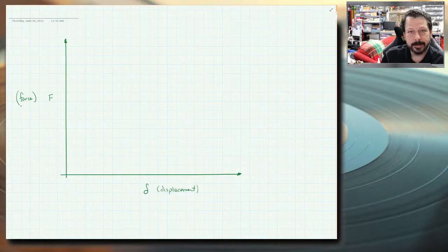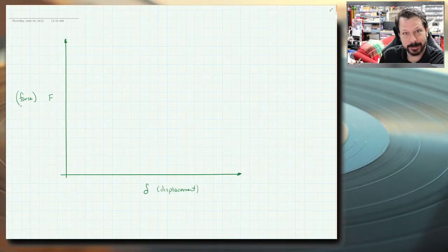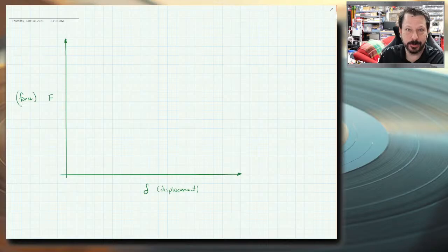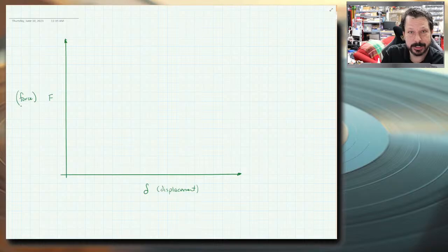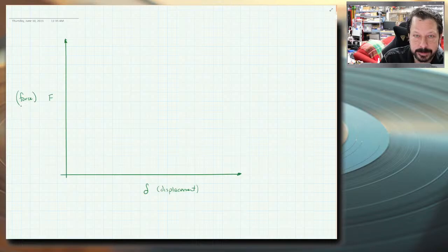Load cell is a calibrated piece of metal with some instrumentation on it, usually a strain gauge or multiple strain gauges. And those strain gauges, I know we don't know what the word strain necessarily means yet, but we will get to that soon. Those strain gauges combined with the load cell, so the strain gauges are part of the load cell. The load cell is capable of telling you how much force is applied to the load cell, and the load cell is connected between the crosshead of the machine and your sample. And so it knows how much force is being applied to this sample.